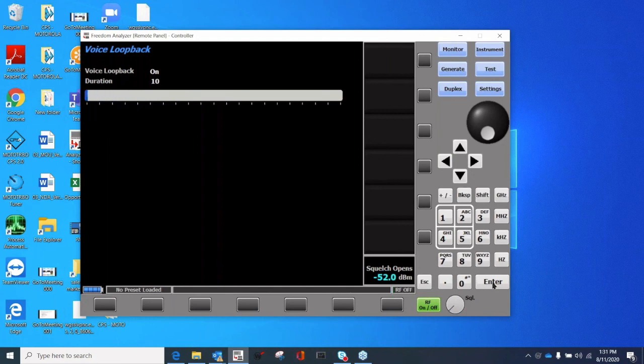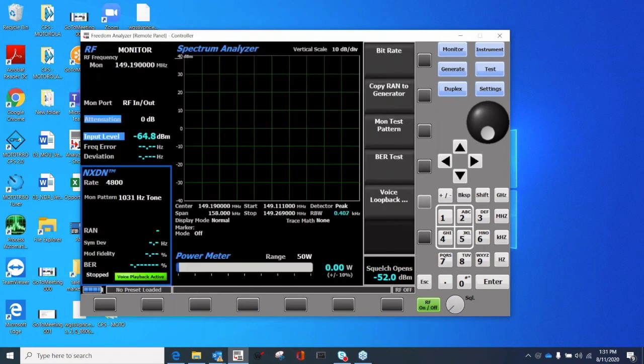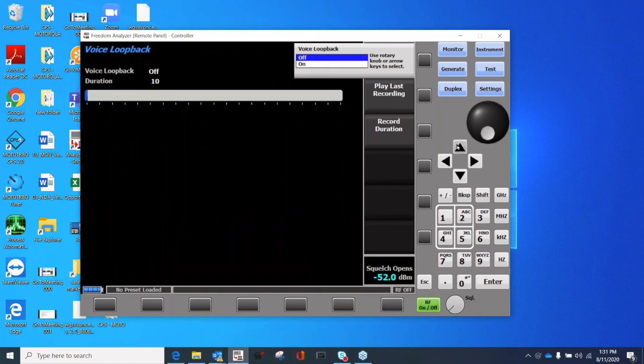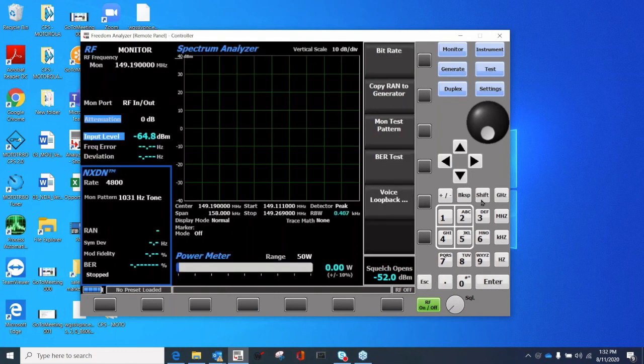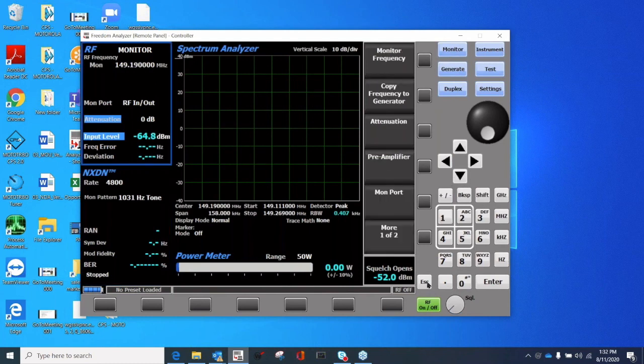Okay, what do we see here? The sensitivity is around negative 120, and you can transmit and record the information without any distortion or missing packages. This is a good way to do sensitivity tests on the radio. Okay, all right, let me take the monitor off here. Escape back to the